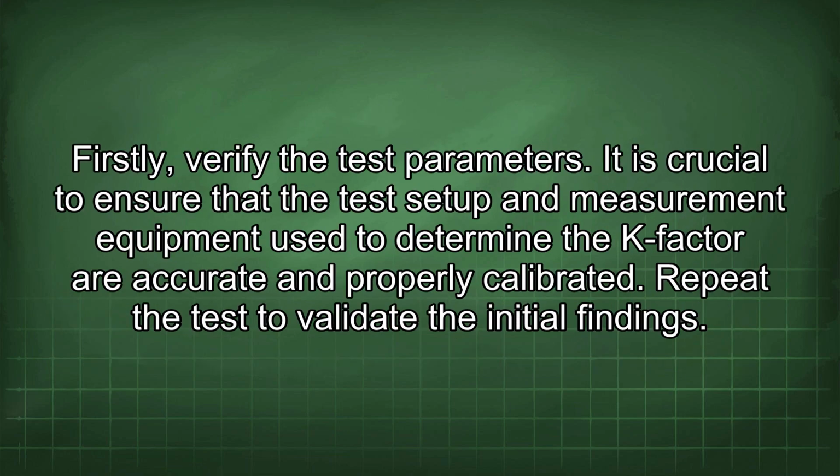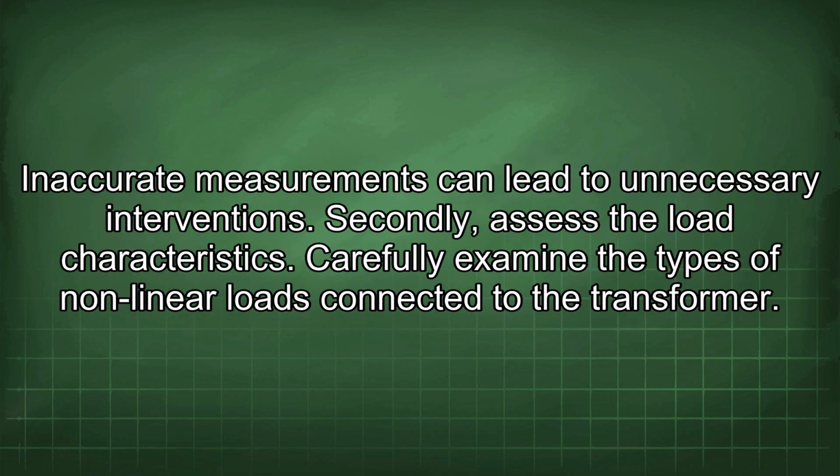Firstly, verify the test parameters. It is crucial to ensure that the test setup and measurement equipment used to determine the K-factor are accurate and properly calibrated. Repeat the test to validate the initial findings. Inaccurate measurements can lead to unnecessary interventions.